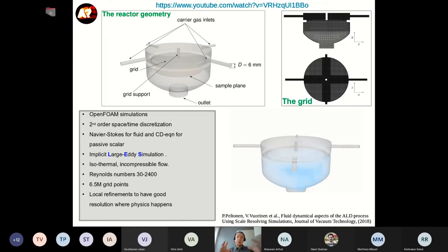There were certain chemical reactions happening inside, and actually this system was used in the atomic layer deposition process, which is a chemical process where different samples are coated. If you have objects or, let's say, electronic components, you can put those into this kind of reactor, and then you bring in certain chemical vapors in different order, and these will create a layer by layer highly conformal coating. So you have different gases in different order, and then these will form a solid, very hard layer on these coated samples.